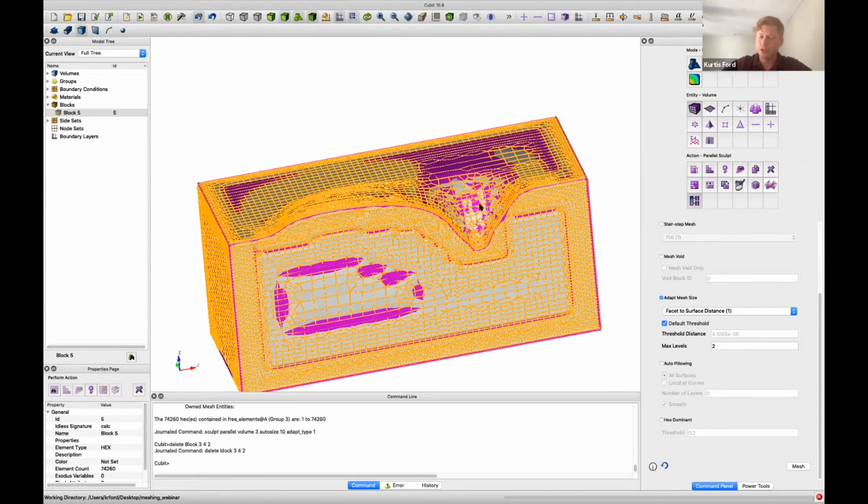So what you could do if you really wanted to use a TET is you could delete your CDFEM mesh, and then you could make a new TET mesh from scratch. There are some people that are trying to smooth the CDFEM meshes, but I haven't seen a mesh generated by CDFEM that is smoothed well enough that I would use a TET mesh.